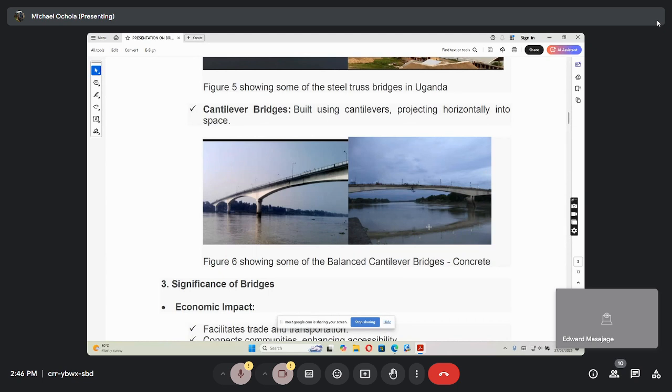One, read about structural components of the bridge. The second one, read about load path. The third one, look at span depth ratio. You have seen from Mosley and Cohen and Ivan, they all talk about, is it a rectangular beam? Is it L over D, is it 20? And then a T beam, is it 18.7? A cantilever, is it 7? Even bridges do have the same thing. So go and begin looking at those basics, but they are very important.